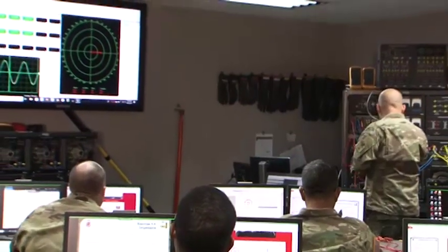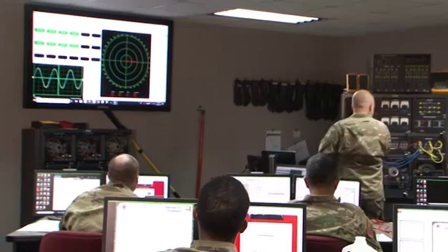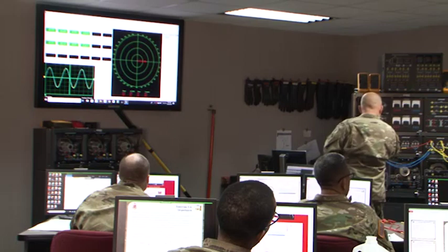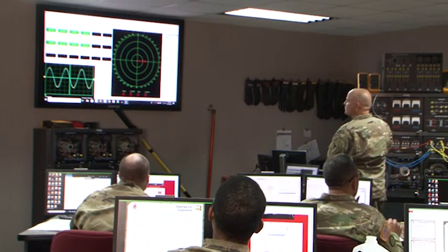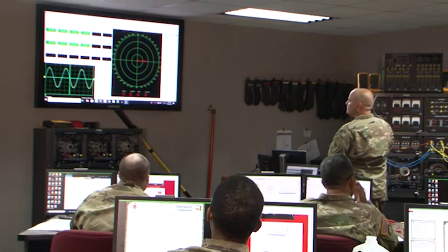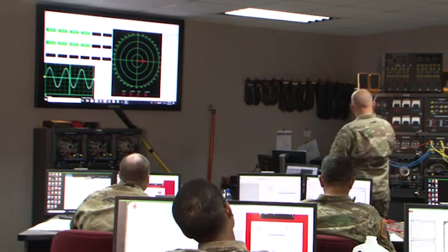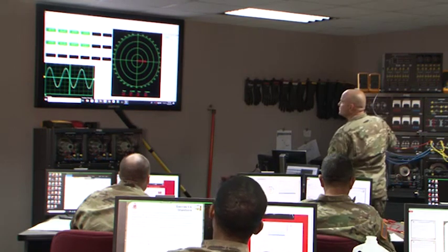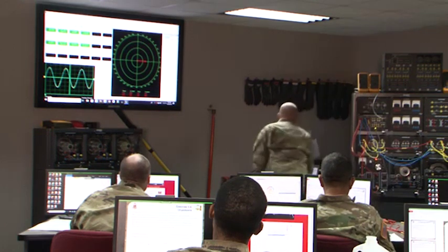Now, I should have some current. What do I not have hooked up right? Let's see, we're going over to here, here to here, here to here. Okay, I'm reading it. Magnitude-wise, my E1 is now just going that, and I'm not showing my source. So right now I'm just looking at the voltage across the resistor. And then E2 is my voltage across the inductor, which let me turn these on so we can see them.